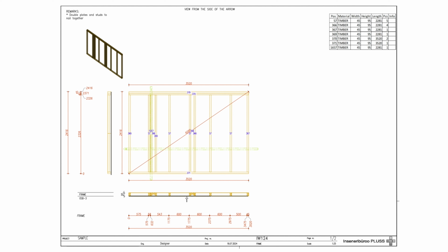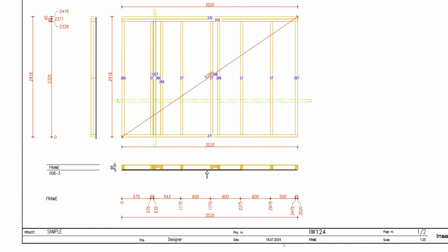Since internal walls cannot be easily distinguished by their inner and outer sides, an additional marking, called an arrow, is used. The view is marked according to the location of the arrow. In the horizontal section below, we see that not all beams are positioned on the ruler. In some cases where posts consist of several beams, only the edge of the beam is marked. There is no need to mark each beam separately, as they are tightly joined to the previous one. This approach keeps the ruler cleaner and makes the drawings easier to read.